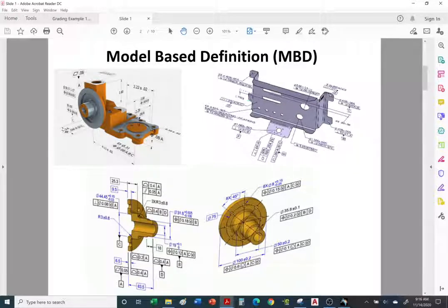So once again, if I measure this off the model, it says 1 inch. Hey, there's no tolerance, so I would have to go into the documentation provided by the aerospace company. And in there, most likely it'll say, hey, any features that are not dimensioned in the 3D model, measure it directly off the model and apply a tolerance of plus or minus 30 thousandths when dealing with inches.